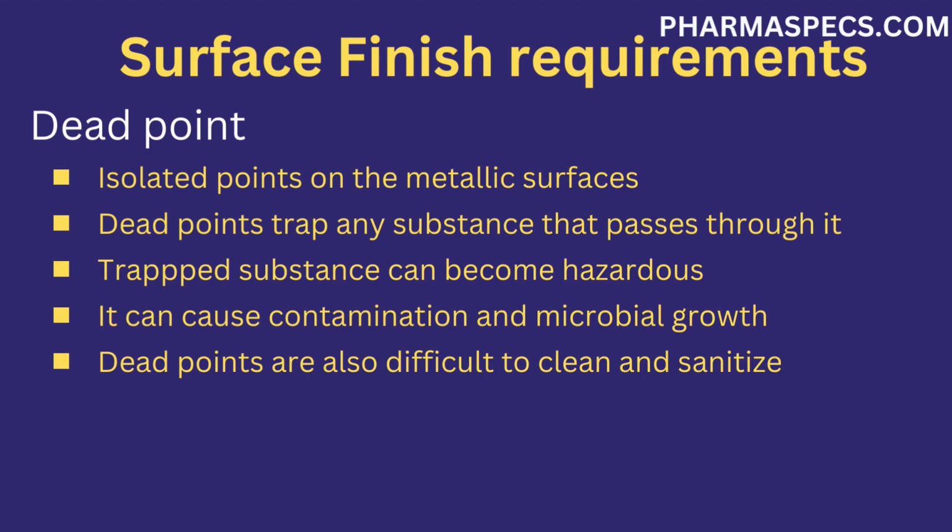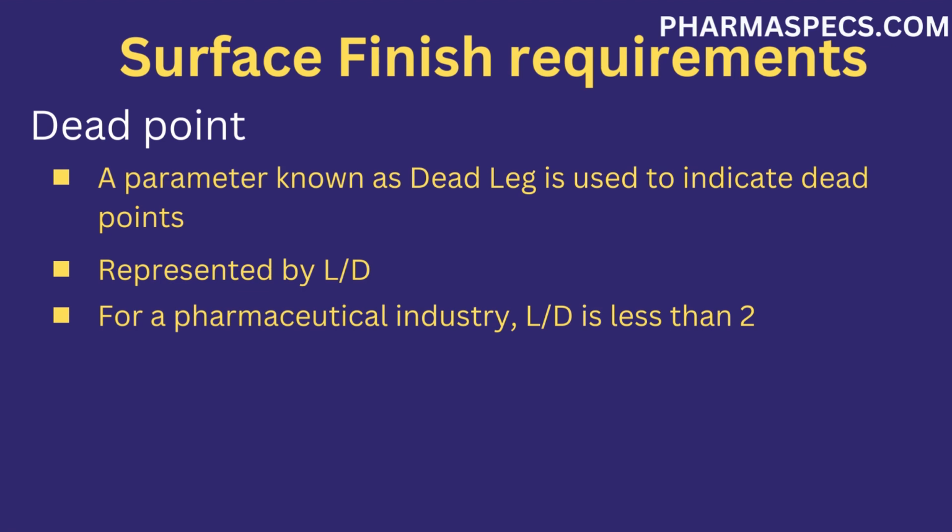The last and final characteristic is the dead point. Dead points are isolated points on surfaces which do not have any passage to and from. Since there is no way to the dead point, the substance can be trapped in it. The trapped substance is difficult to move and locate from the dead point. The trapped substance can cause contamination and enhance microbial growth. Dead points are also difficult to clean and sanitize.